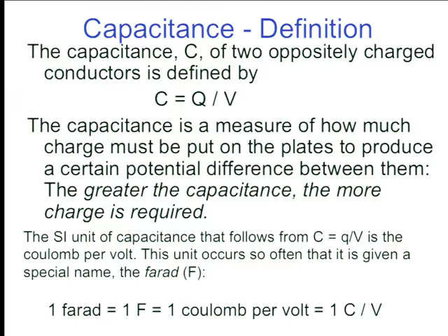Okay. The current at first will be all the voltage across the resistor. So the current here at the beginning is going to be the EMF over the value of that resistor. That's going to be the initial current up here, because what happens is that the current runs through here. Fast changes run through a capacitor, and the current will be running through this resistor. So that's how it basically looks. This is the I. Now the I on the capacitor is actually equal also to the I in the resistor by continuity of current. Whatever flows through here flows through here. So those are the same.